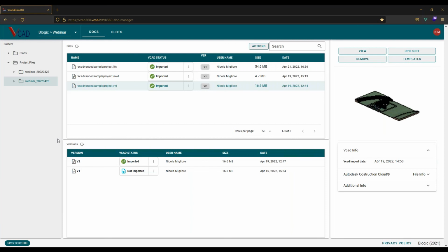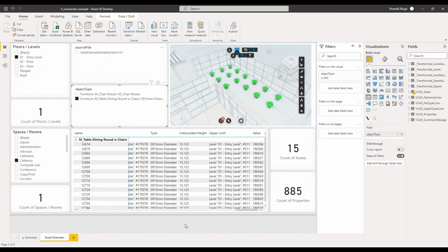Finally, the Navisworks, as we already said, has the best performance out of the 3, especially for large models. It has the best federation because it allows you to federate models coming from different disciplines, but even different file formats. So a Revit file can coexist with an IFC file inside of a Navisworks file and communicate together. That's a definite plus. However, because it needs to be able to do all of this, it's very structured, it's very normalized, so retrieving some information may require some data transformation on the actual report side of things.